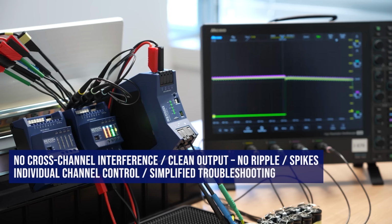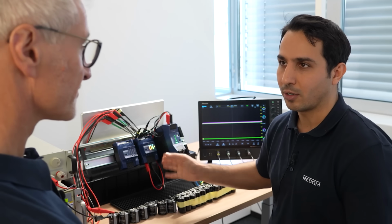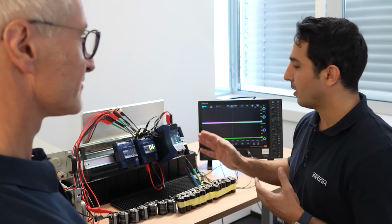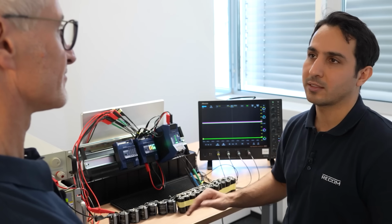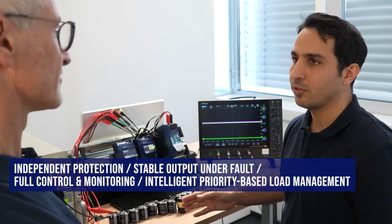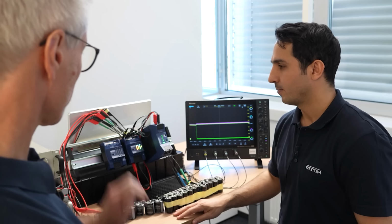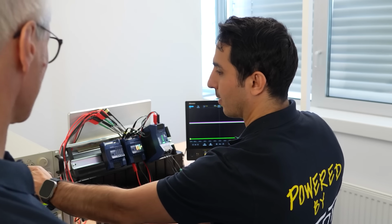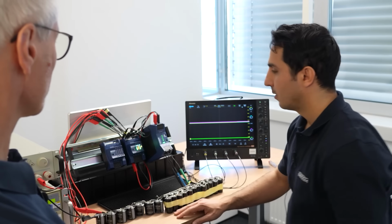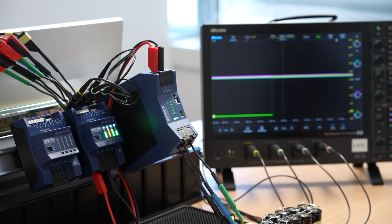You see here, channel 4 got isolated, because channel 4 has the lowest priority in our architecture. Okay. So in our architecture, we have a backward priority listing. So channel 4 has the least priority, then channel 3, and so on. Okay, and what happens if the load comes back to 5 amps, to the standard load? Yes, good point. Now when we put it back again, it recovers itself.